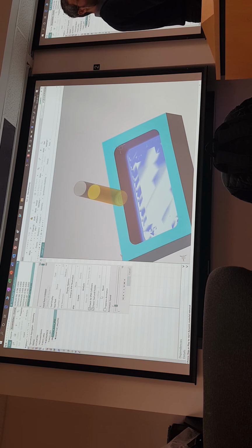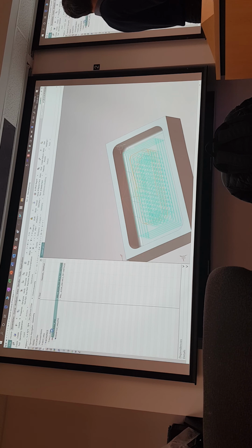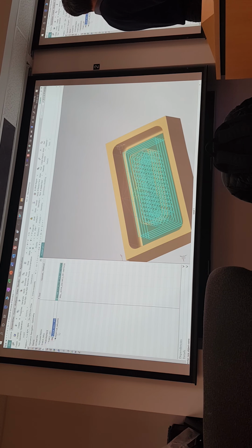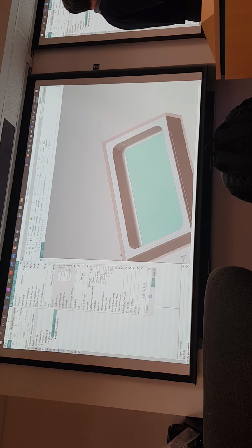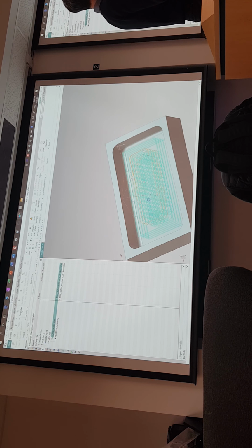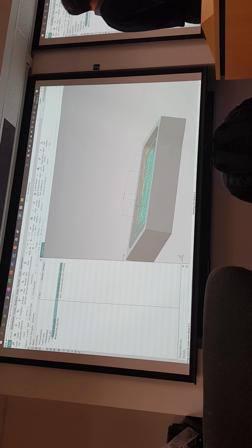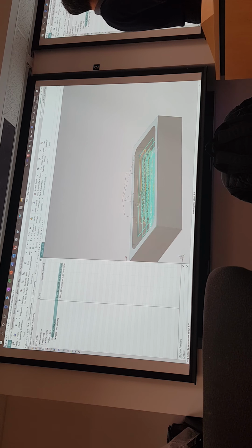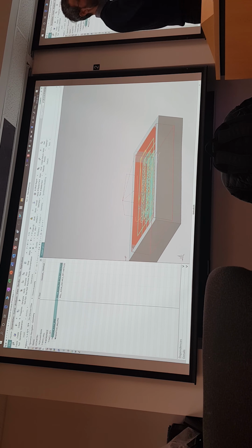Please explore the software. So with adaptive milling, you can take light radial cuts and you can go full depth. This one you can take maybe heavier radial cuts and do it in multiple Z levels. And you see here, instead of using a helix to approach the material, I'm using a linear ramp.